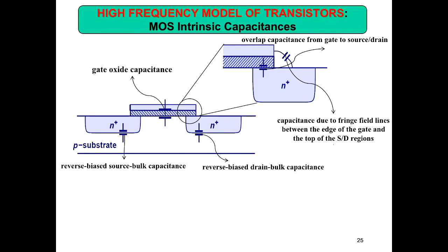But then you design the amplifier and pump the signal. At 500 you are getting a nice signal, then at 600 you will see a little bit of a problem, maybe attenuating the output. But once you are around 1 gigahertz, you will see a big effect, because all these parasitic capacitors in the transistor will come into account. Not only these, but also the parasitic effects in the PCB. Whenever you have a PCB, it also has parasitic components, and all these things come into the picture at high frequencies, around 1 gigahertz. So that is high frequency.